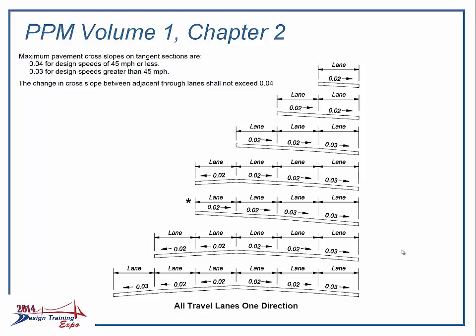In either case, the typical cross slope, such as a 2% or a 3% or even perhaps more percent if that's what the user inputs, can be the target design elevation in a typical tangent section. In super elevation, the design cross slope is read from the super elevation parameters within Civil 3D.